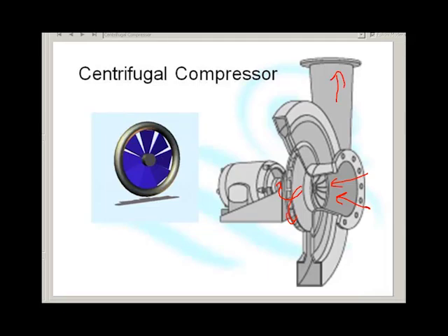Centrifugal compressors are lovely. They're not as efficient as screws. They're very, very quiet. Screw compressors scream like banshees. They're horrible things. But a centrifugal compressor is lovely and quiet. There's no oil involved anywhere. It just runs nicely. To unload a centrifugal compressor, we have these vanes.